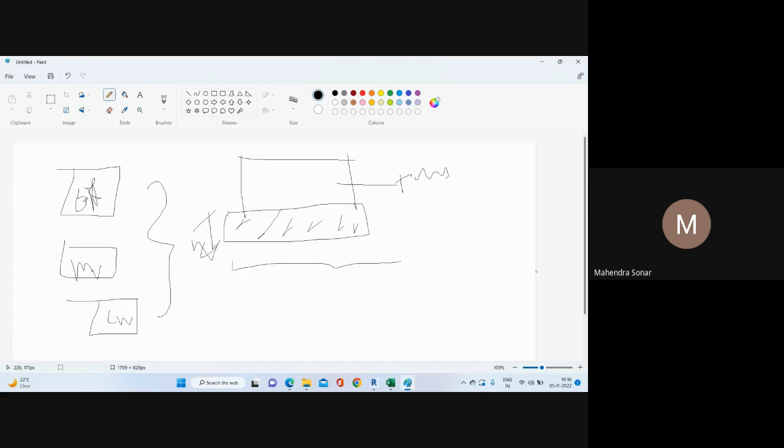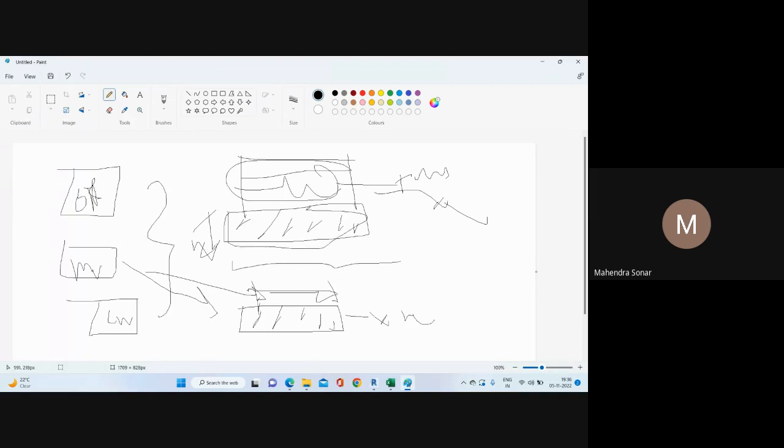Once you model in your structural drawing, the mechanical discipline also uses your structural model. So he will xref your model. Once he xrefs your structural model, this plane comes in as an xref in the mechanical model, and then he can add the tank on this. So he is working on all the mechanical parts. Similarly, we will xref this mechanical drawing, so this mechanical model as an xref in our drawing, and we can create our structural drawing here. Then similarly electrical also.